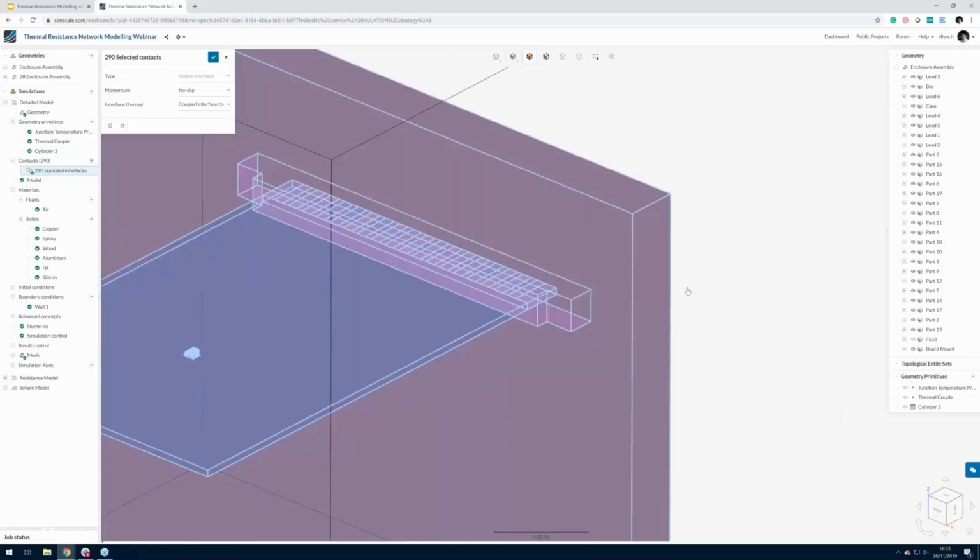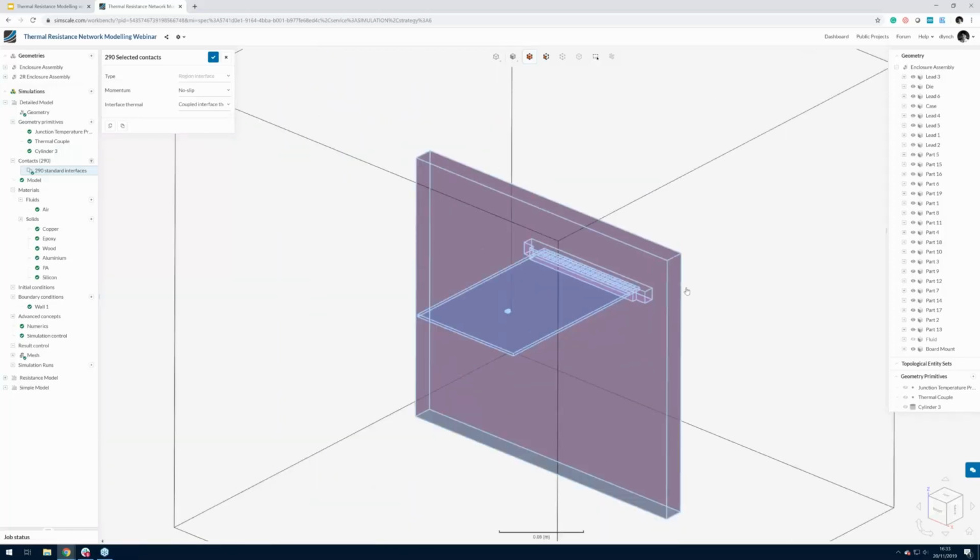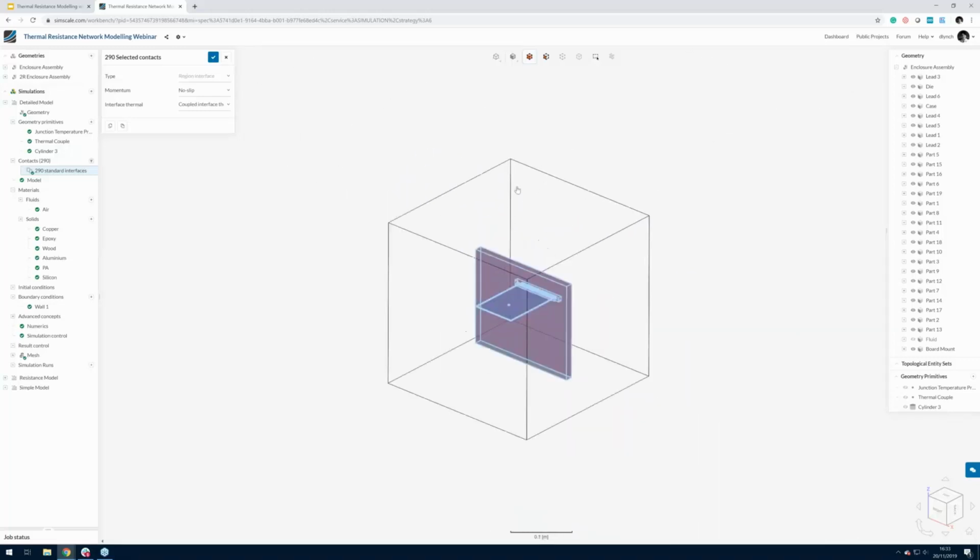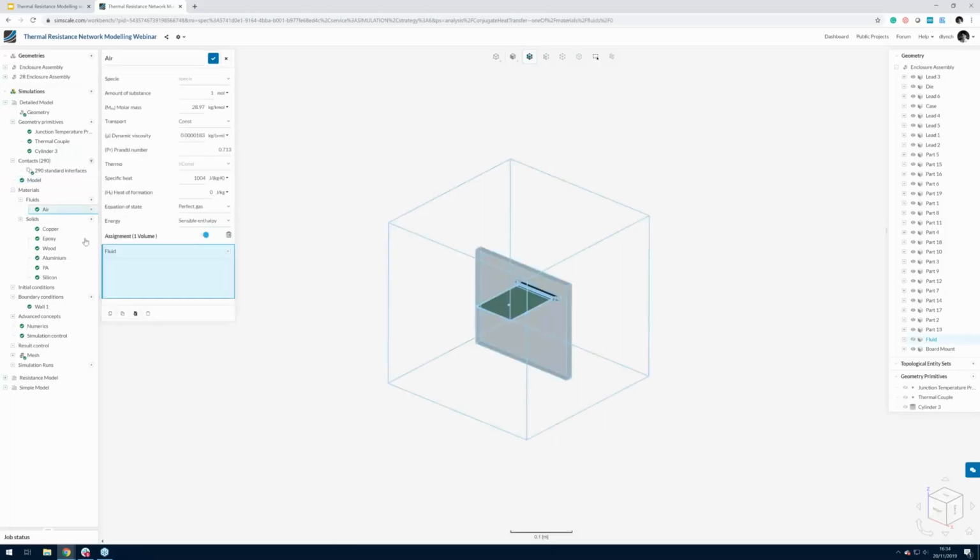And this is all done automatically, so you upload the geometry and it picks it up. So huge headache off your mind if you're familiar with any other CFD software. The model, in this case, it's very important to make sure that we define gravity being in the negative z direction. The fluid in this case is air, and that's assigned to the fluid domain.